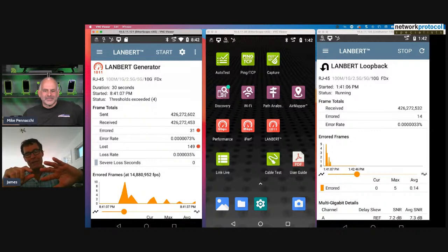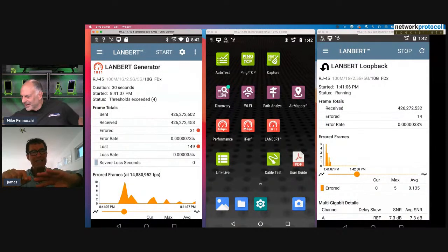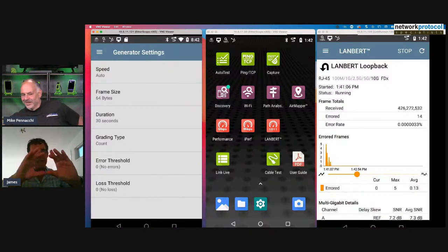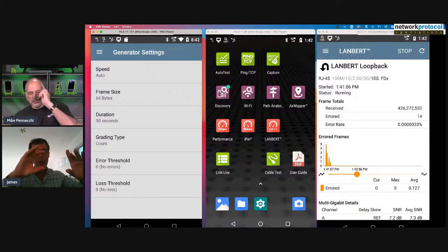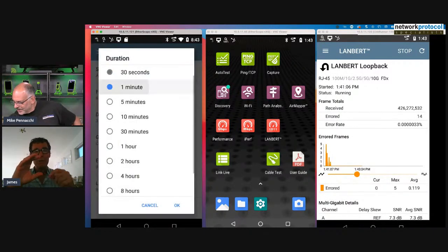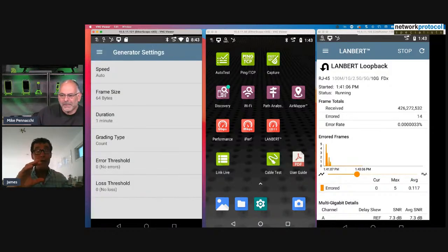Well, when they invented 10 gig Ethernet, they went to a PAM16 encoding. So now there's 16 levels in that same voltage swing that just used to be a 0 or 1. So now there's 133 millivolts between every discernible level, right? And that's where the PHYs, the DSPs, have gotten so much better about pulling all that out.